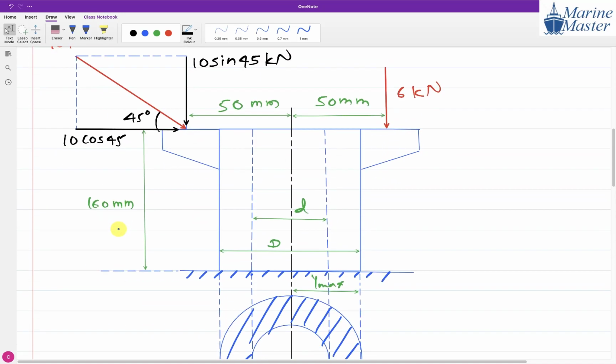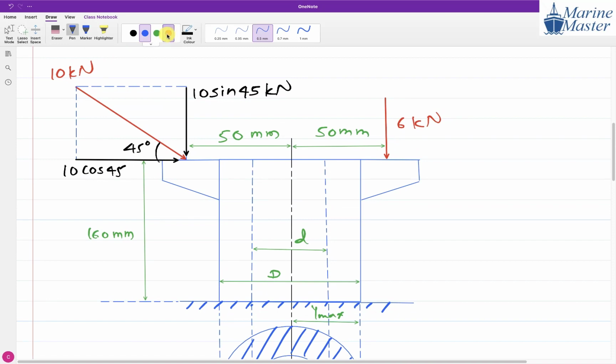Now here everyone, whenever we want to calculate in case of the eccentric loading scenario, we always calculate a moment with respect to this bottommost point. This is like a cantilever beam scenario, and I told you for a cantilever beam, maximum bending moment is at the fixed end. But in the fixed end also, which point you have to select? Center point. Remember this point.